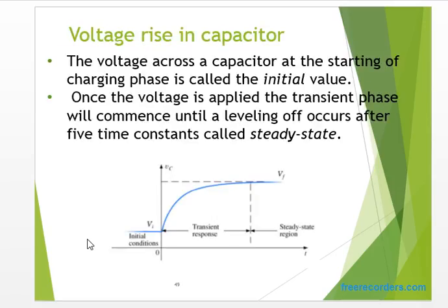How the voltage rises in capacitor? You see, initially there is no voltage and this is 0. As the time passes, capacitor charges and voltage of the capacitor is settled, and this is called as steady state condition. Time taken to rise from 0 voltage to final time is defined as rise time. Capacitor is fully charged after crossing the rise time, and this is defined in terms of time constant, which is normally 5 time constant.